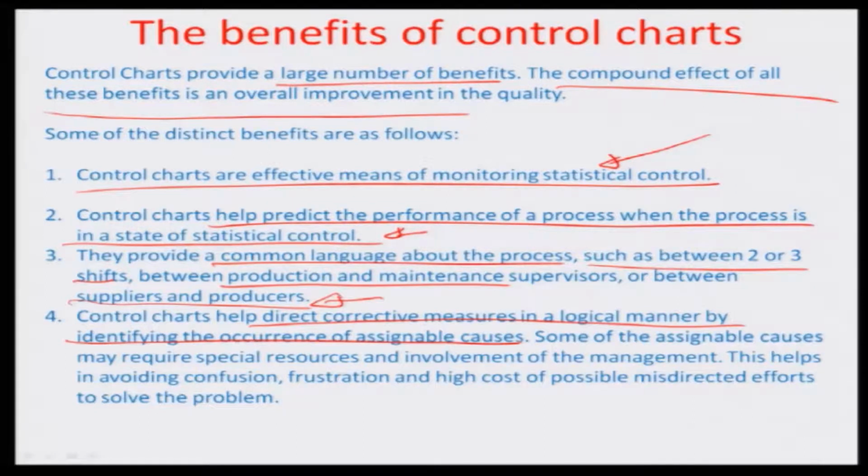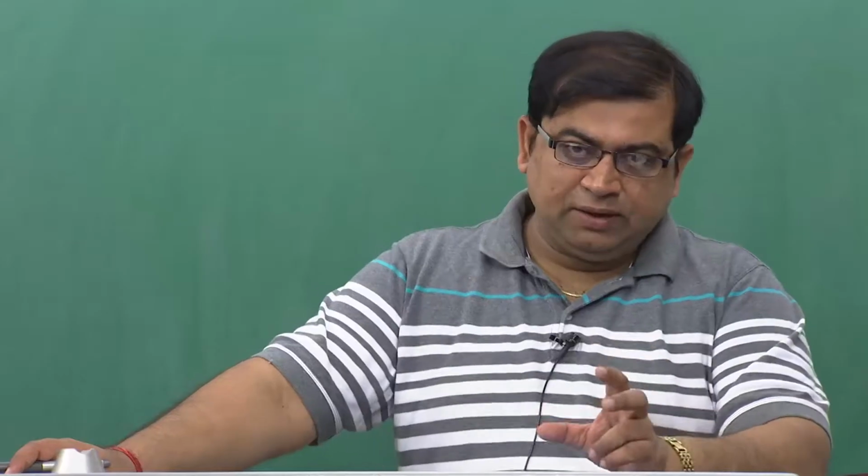You can pinpoint, again using the other tools of QC that I have illustrated earlier, why a certain defect is coming. So if you have a recording of a particular defect going out of control, you can easily focus on that defect and then do the man, material, machine, method analysis to see what the different causes are and try to eliminate those root causes, or you can even do FMEA, as a matter of fact, and try to see what the highest priority defects in the system are.